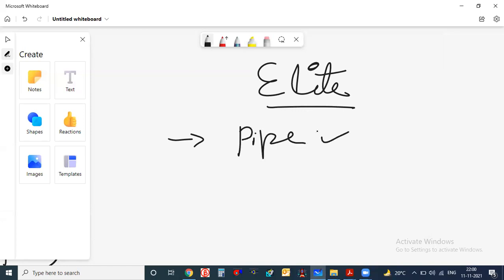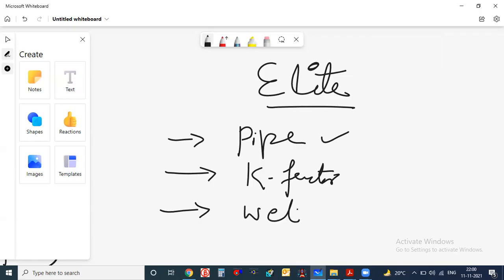We have to give the category of pipe, like 1, 2, 3, 4 number we have to give. This is the first thing. Second thing, you have to write down the K factor in the Allied software. The sprinkler name and all we don't require. The name of the sprinkler is not required. Means type of the discharge is required, like wet or dry. This is required, third point. And next you have to give the light hazard, ordinary hazard or extra hazard.